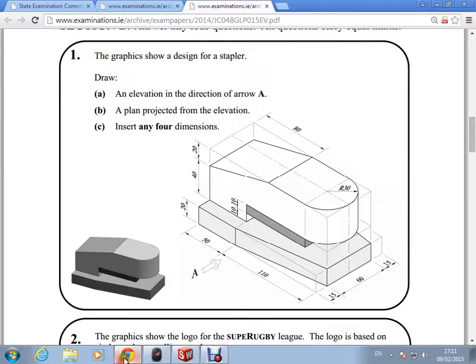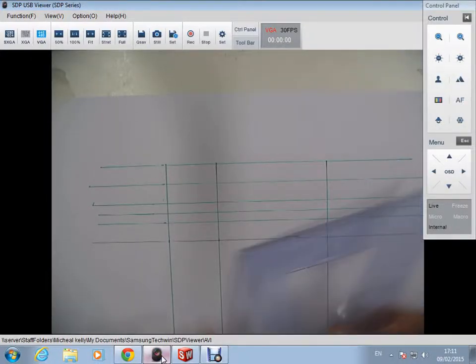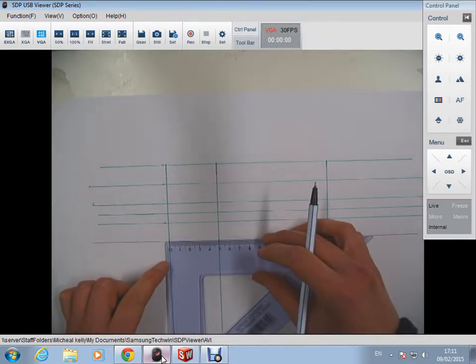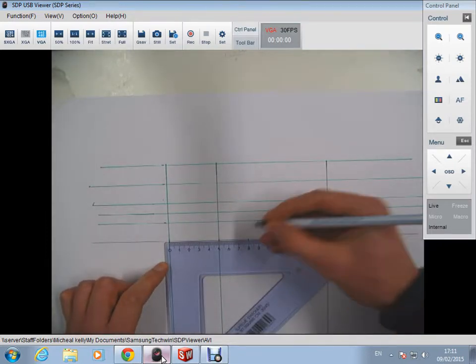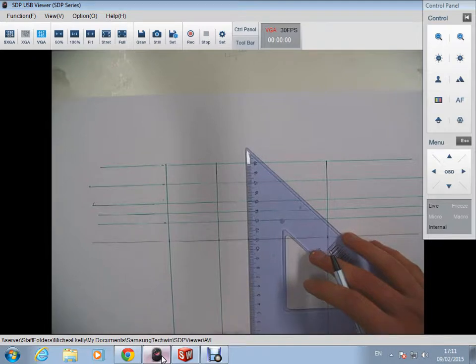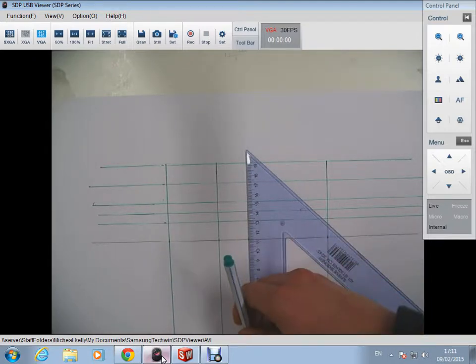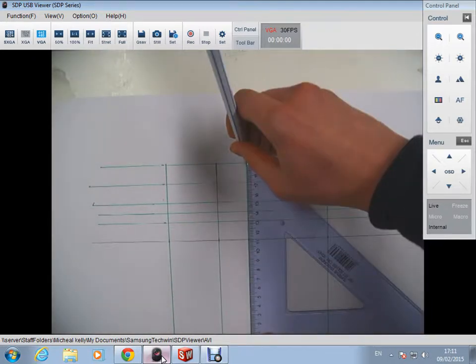So we'll look back to our drawing again. So that has given me this distance here and the full width. I also need to mark over a distance of 80 millimeters from the left hand side over. From the very edge that 80 millimeters is coming from. Take that line down the page vertically with my set square sitting on top of my T-square.